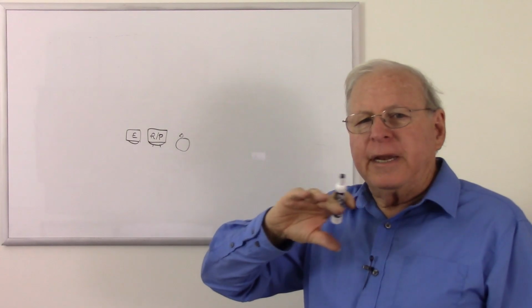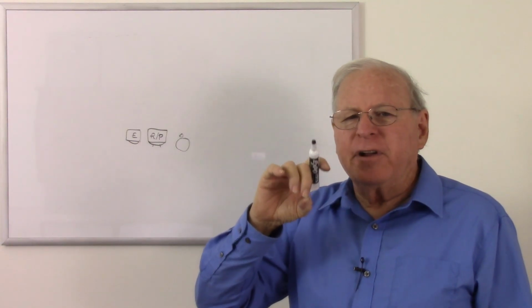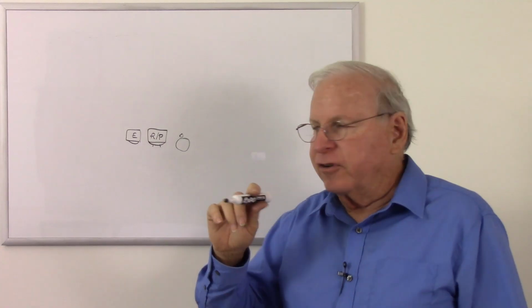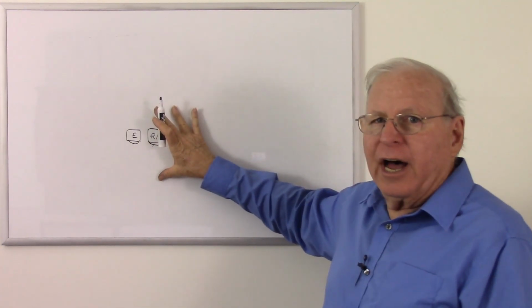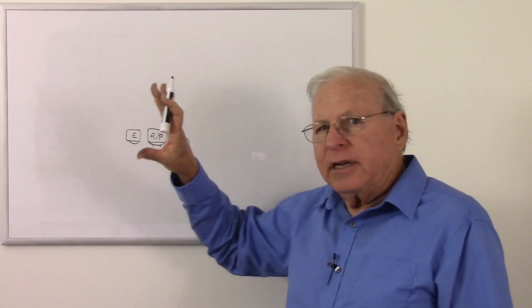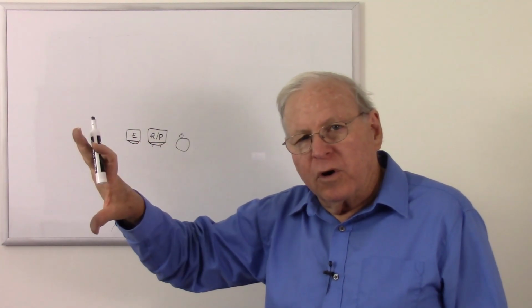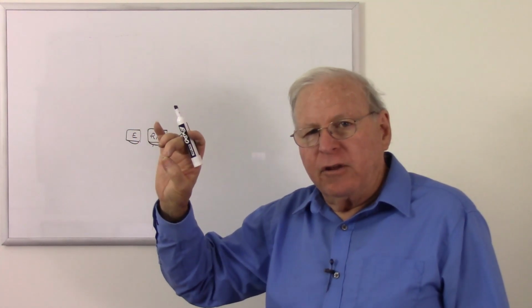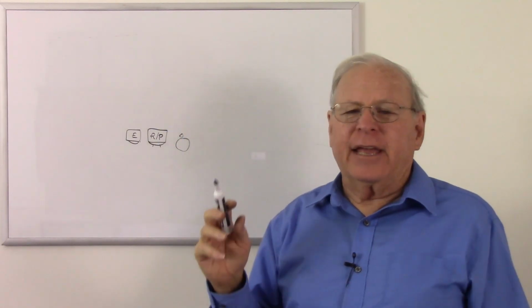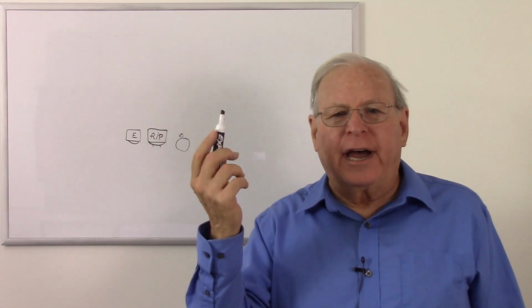So what Dolby did is basically something very similar to what they did with vinyl records with the RIAA equalization. Dolby boosts the high frequencies, and so if you have a tape player that records in Dolby, you record it using the Dolby noise reduction, and when you played it back it sounded very tinny because they had boosted the high frequencies.